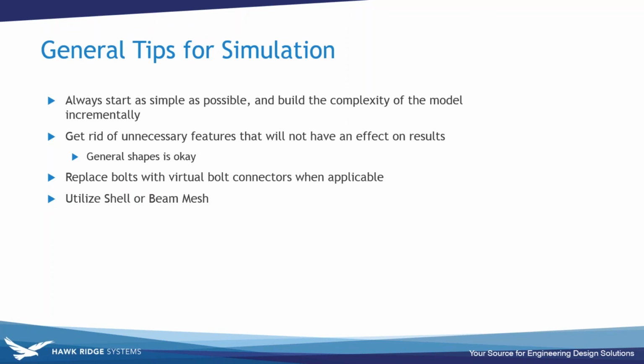Right now, if you model with normal SOLIDWORKS features, you're going to get a solid mesh. That may be an issue when you're running analysis on a frame, or on very thin components like sheet metal parts. Using shells and beams will make your life a lot easier in terms of the complexity of the overall problem. All right, so those are some general tips for simulation.